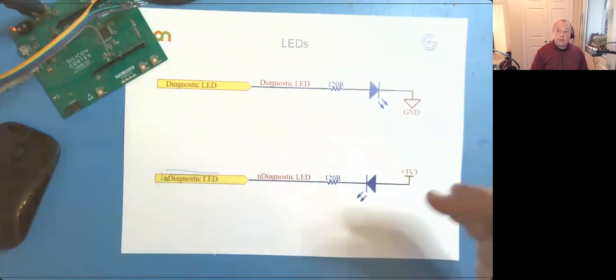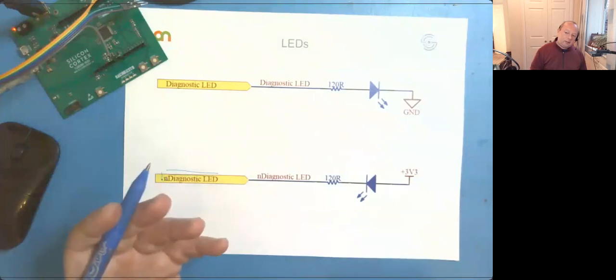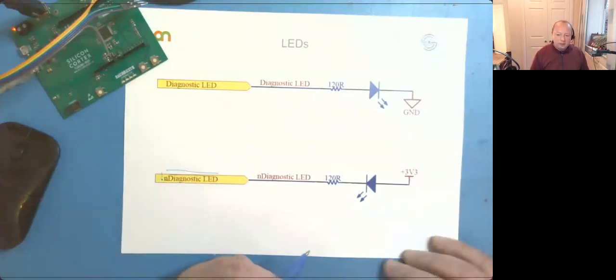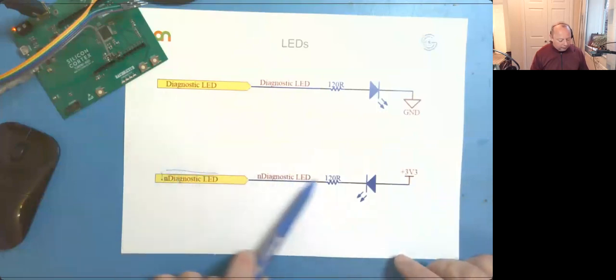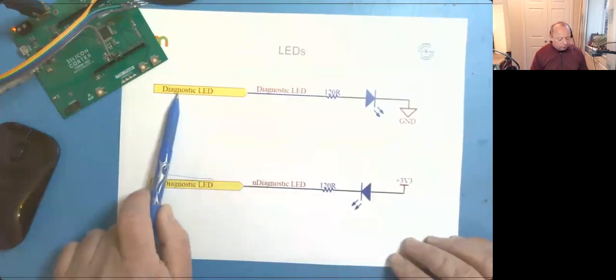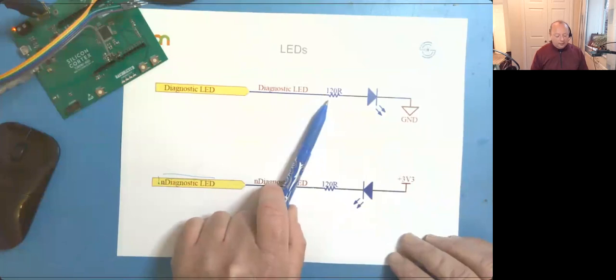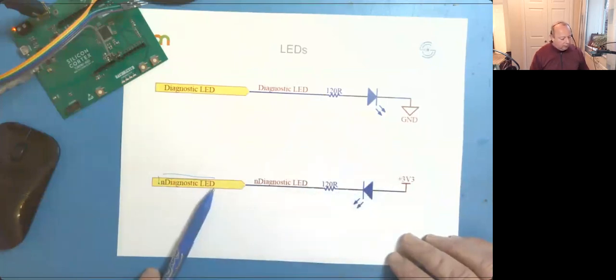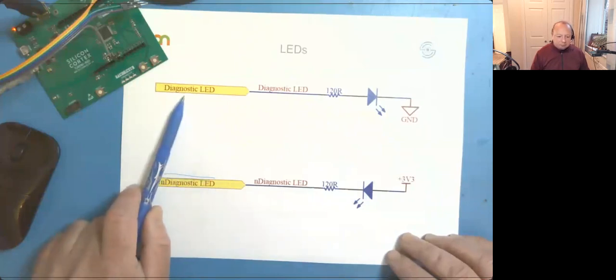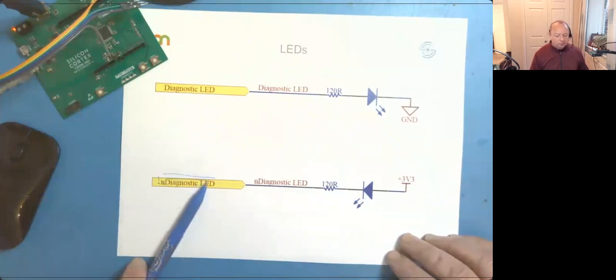And then my code and the schematic tie up a lot easier, so I can see what's going on. The other thing to bear in mind with a current sink, as this one is, as opposed to a current source, is that generally you can sink a lot more current than you can source. So that's just another thing to bear in mind.